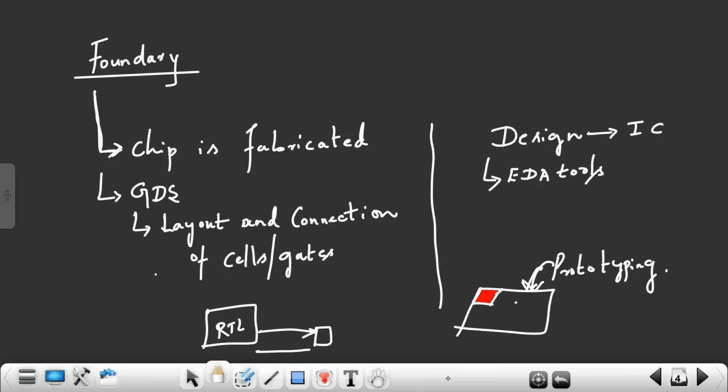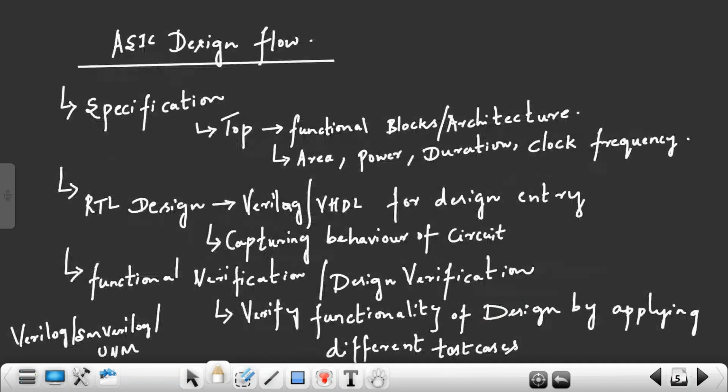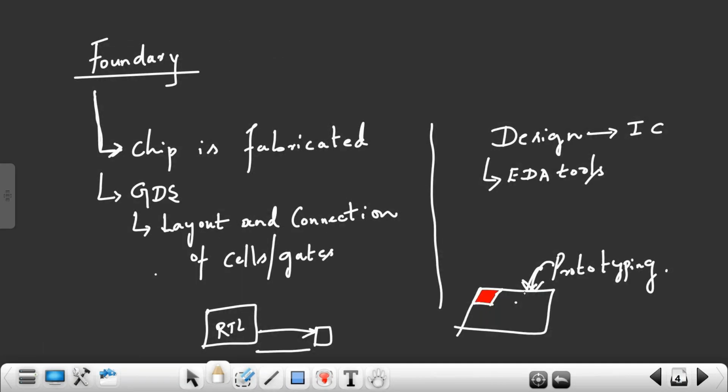So they can use it for prototyping. Prototyping means testing this RTL code, whether it works as an ATM machine or not. We are doing functional verification, which is done on a software tool, not on hardware. If I want to test on hardware, I can easily dump it on an FPGA and test whether it is going to work fine.